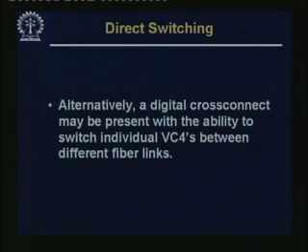So, between different fiber links, that means there is a digital cross connect. If you have a digital cross connect at the optical level, the advantage is that you need not go into the electronic domain at all. One of the advantages is that you are handling a very fat pipe, that means a large number of channels, and you can just switch them from one fiber to another simply in the optical domain without doing any kind of processing, and that is always an advantage.